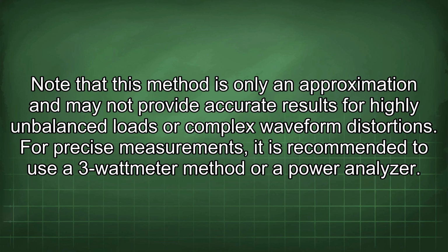Note that this method is only an approximation and may not provide accurate results for highly unbalanced loads or complex waveform distortions. For precise measurements, it is recommended to use a 3 wattmeter method or a power analyzer.